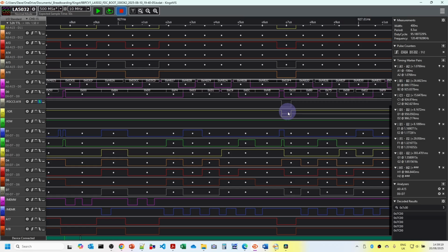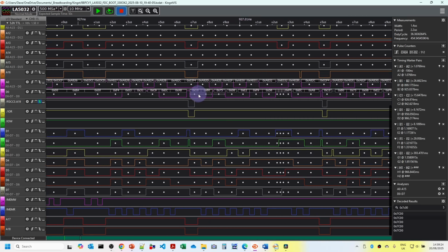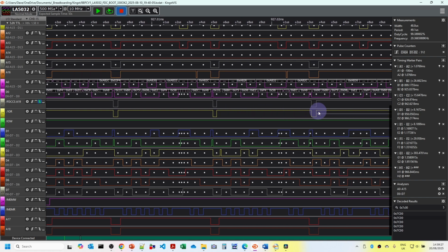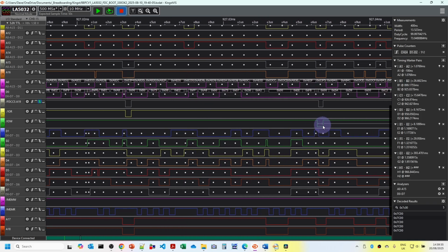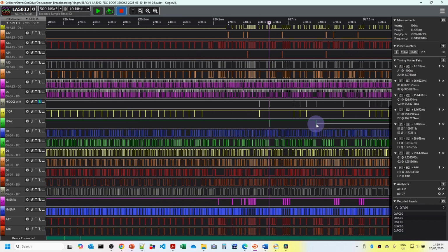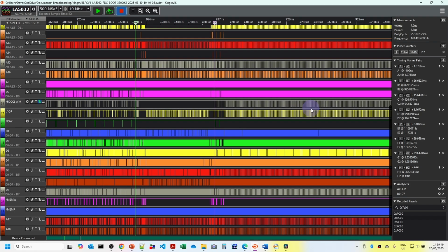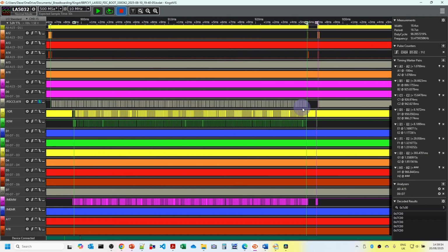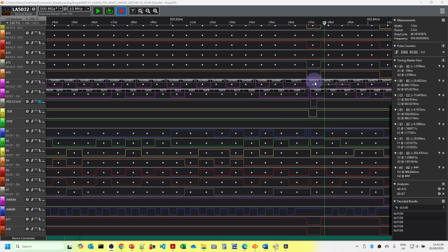We have to poll the status here, so you can see that once we've sent the command, it's not ready for any input. The 10 means it's busy, but it isn't ready for talking to it. When it shows 90, it means that it's still busy doing a command, but we can now send some data to it. In fact, we need to send it the drive number to tell it which drive we want. Once we send it drive 0, which is drive A, it'll go off and start. There you can see that we're then polling the status for quite a long time here, until towards the end of the status polling, we see the first bit of data returned.